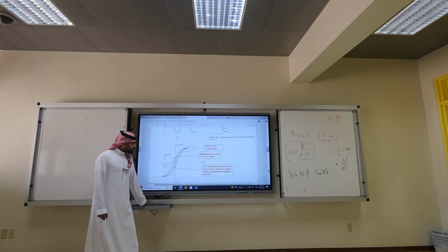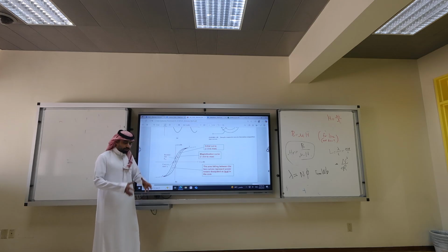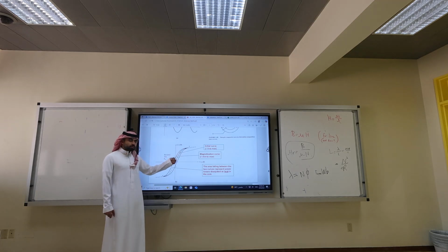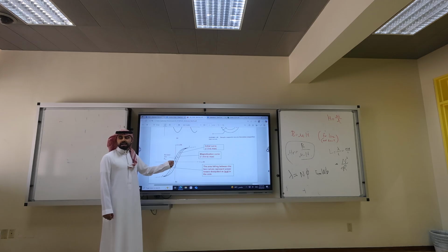Anyway, you're spinning in a loop called the hysteresis loop. In short, if you apply a current on a coil with a core, you will magnetize the core. Even if you remove the current back to zero, the core would still be magnetized by a quantity called residual flux. You want to get rid of it, apply a coercive force until you reach a zero flux. Then you stop. If you keep going, more negative current. What does negative current mean? The opposite direction. Reverse direction or 180 degrees phase shift. Go here. Maybe you're lucky, come back. Maybe you're lucky, don't come back.